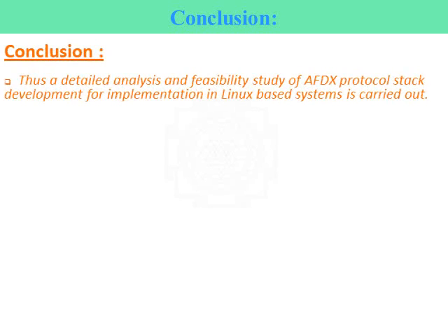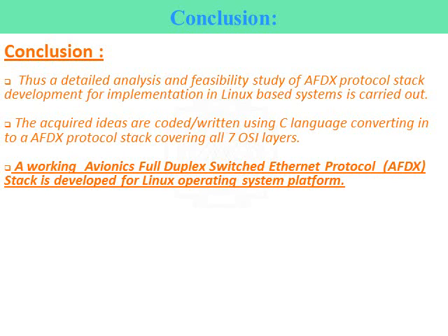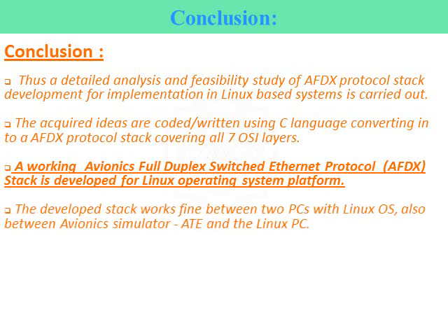And these are all my conclusions of the project. A detailed analysis of the AFDX protocol has been done. A feasibility study on implementation on Linux has been done. And coding in C for all 7 layers of the OSI model has been done. A working AFDX protocol stack has been developed for the Linux operating system in C language.